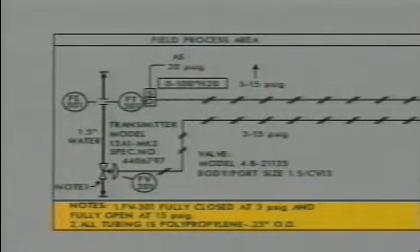You'll also find two types of notes on the diagram. Notes can be general or specific. General notes pertain to the whole loop, and are written at the bottom of the diagram. Specific notes, those that contain information about a particular instrument or component of the loop, are found on the body of the diagram.